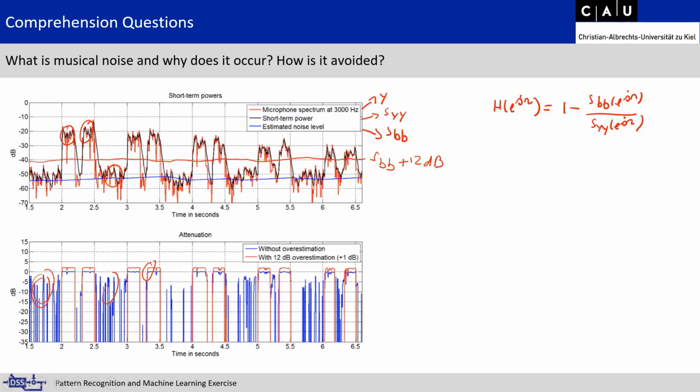and we have constantly low values in the noise-only phases. And since this incorrectness of the noise estimate should not be arbitrary, we can use the output of our correct estimator and always add a constant gain. And this is exactly what is achieved by the so-called overestimation factor K over, which is added in the frequency domain solution.